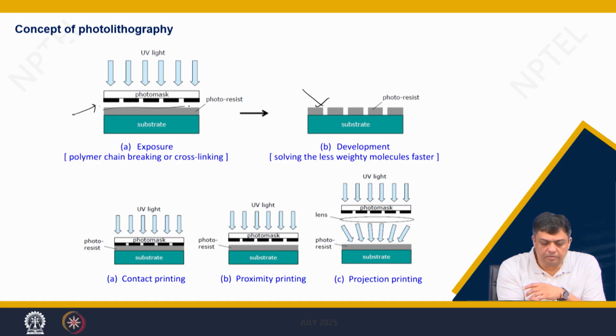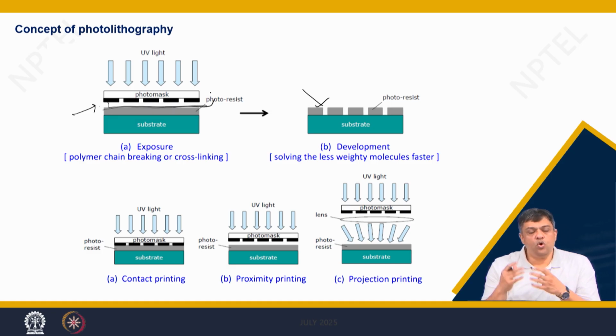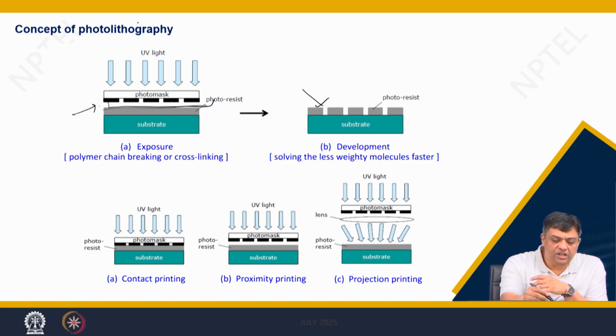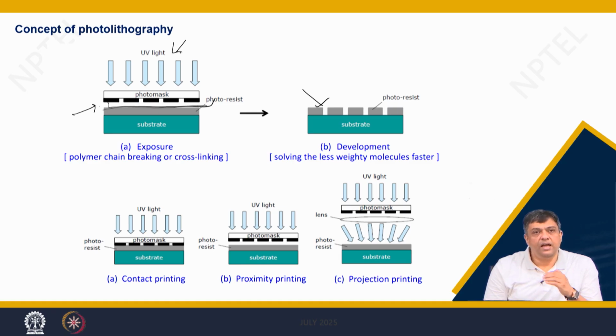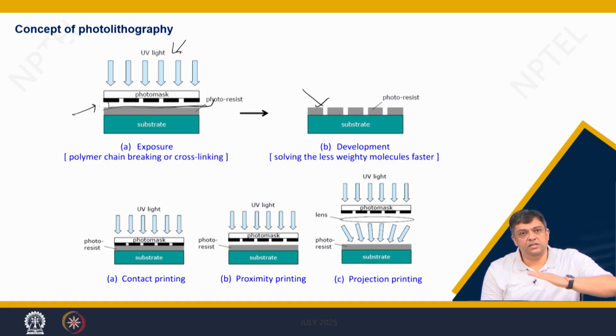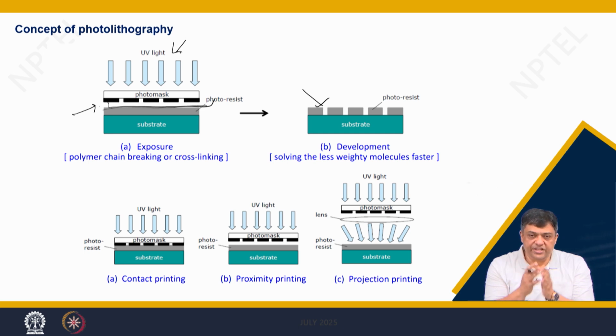If you have the light falling on the mask and then you have the patterns below getting exposed, the molecular weight will change, the resistance will change below. You can use a developer, remove those areas, fix it with a mask, and then etch out the remainder materials which are not required, remove the final etching mask, and you will get the patterns which you are looking for.